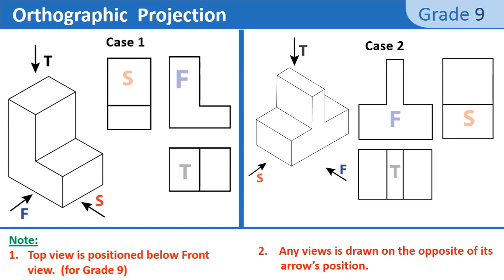There is a difference between the positioning of the orthographic views of the two isometric blocks, as the front view and side view directions are different. So, you must be very careful before starting to draw orthographic views. And by the way, it is advisable to draw a sketch before drawing the orthographic views using instruments.